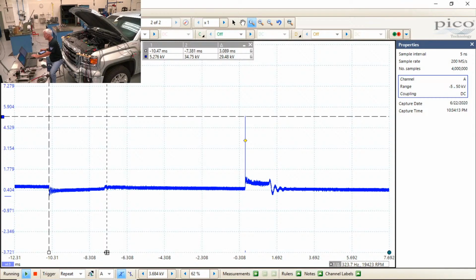That doesn't diminish the magnetic field because it's still there, and they haven't turned anything off or collapsed it. So at this point, that's current limitation. And then right up to the point where the trigger is, that's when they turn the coil off. They shut it completely down, and that magnetic field collapses. The collapse of the magnetic field induces voltage into the coil.